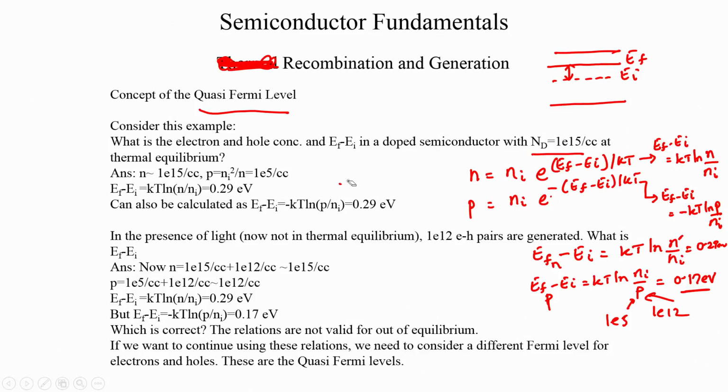Okay. So with this we come to the end of the study on recombination and generation, and we now have the tools to understand how dN by dt is affected by recombination generation mechanisms. And we will now embark upon establishing a concept which is called the continuity equation, or a complete budget of the carrier counts in the volume, which was the big picture we have been discussing, and we will use that to study semiconductors in various conditions.